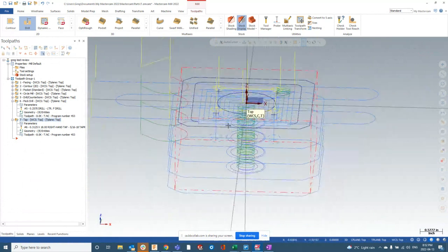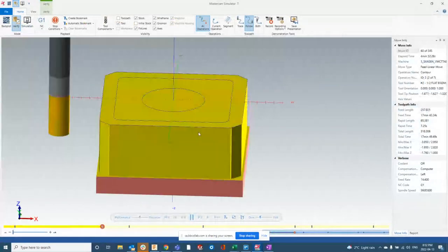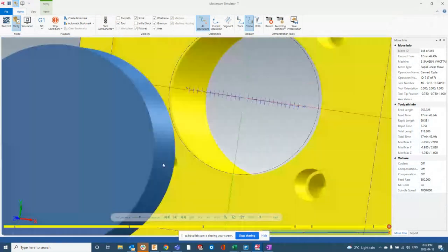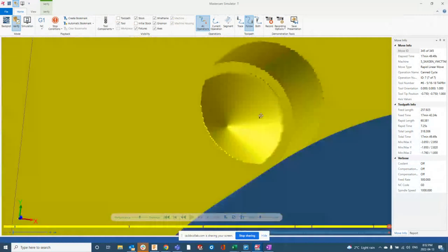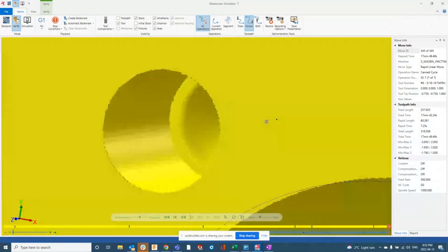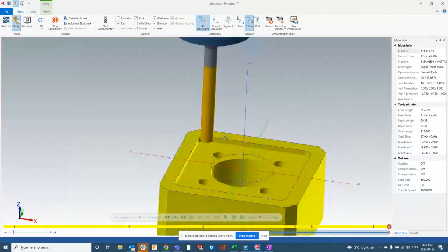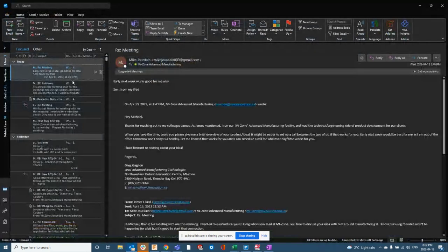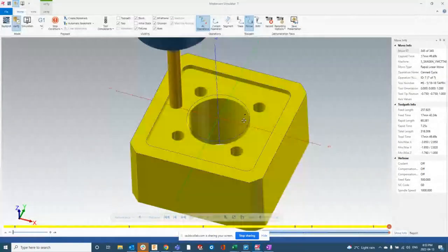Okay, so now we have it: spot drill, drill, tap. Perfect. So let's watch that. It's beautiful. You can see the drill goes a little further than the tap does. Tap goes up to here, the drill goes further. That allows the tap some room, right? And again, companies call for ½ inch threads. They don't care how deep the hole is normally. Sometimes it might matter, so sometimes companies will tell you exactly how deep to drill, because it kind of takes out integrity of the material. So there we go. That's most of the assignment.